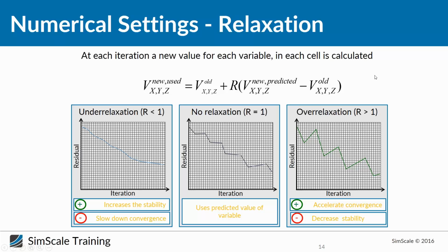In the best case, you will use exactly that value that still gives you maximum convergence speed and is exactly at the point before starting to become unstable. And yes, that's basically what we talk about. In general, most of the time you will use under-relaxation, even for a good mesh, and then you have to decide if you want to run 0.1 or if you can go up to nearly 1. This should depend mainly on your mesh quality. If you have a good mesh, you need, let's say, less relaxation, and that's what we call relaxation.